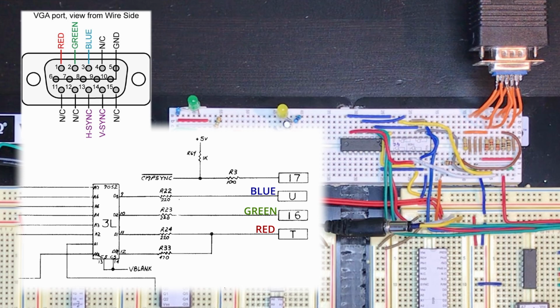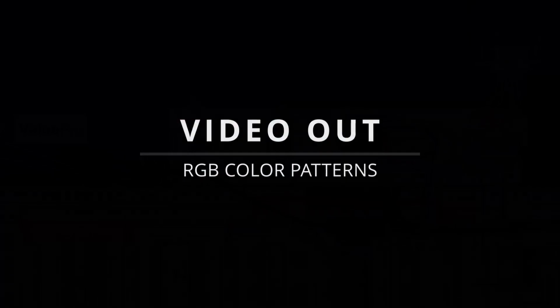We won't get into how this chip, which is actually a programmable color chip or PROM chip, is working in this episode. We'll cover that next time. For now, all we need to know is that we need to trigger the red, green and blue at a set time and when we're not in the H-blank or V-blank time period.